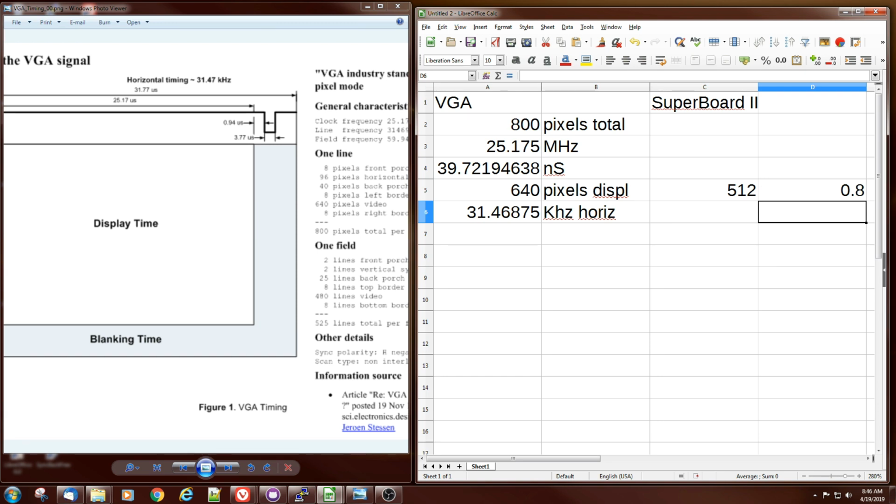So if we change the clock frequency from, and these are actually doubled because it's running at 50 megahertz for this particular setup, but if we tried to do that same factor to the clock, we should be able to determine a clock and set the PLL inside of the FPGA to generate a slower clock rate, which should lengthen the line out. That would be a rate of 50 times the 0.8, which is around 40 megahertz. That's a good rough start for calculating the correct number.